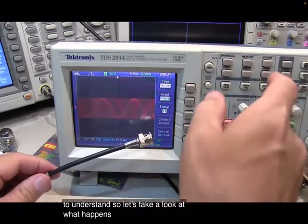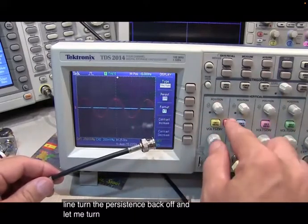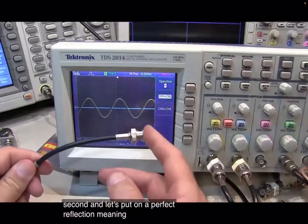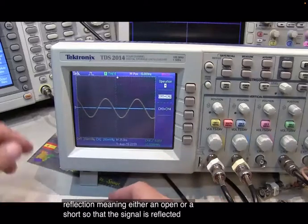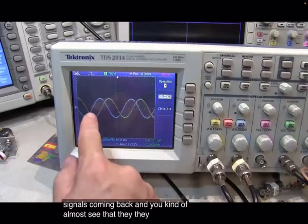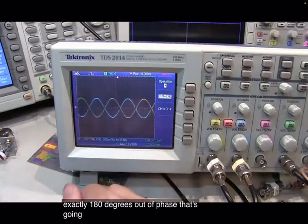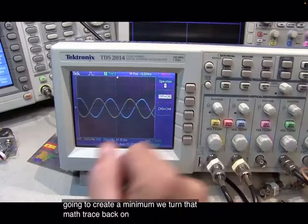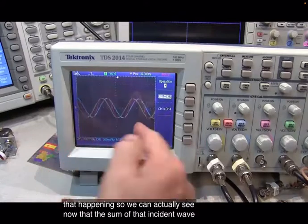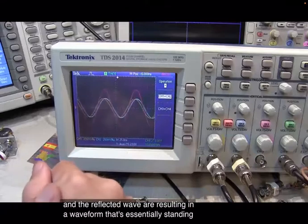So let's take a look at what happens when we misterminate the line. I'll turn the persistence back off, and let me turn the math off for a second, and let's put on a perfect reflection, meaning either an open or a short, so that the signal is reflected at full amplitude. Now I've got these two signals, and you can almost see that they add up right on top of each other. That's going to create a peak, and then when they're exactly 180 degrees out of phase, that's going to create a minimum. If we turn that math trace back on, we can actually see that happening. The sum of the incident wave and the reflected wave results in a waveform that's essentially standing still.